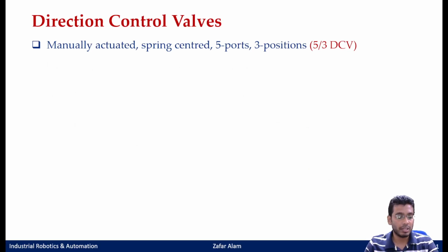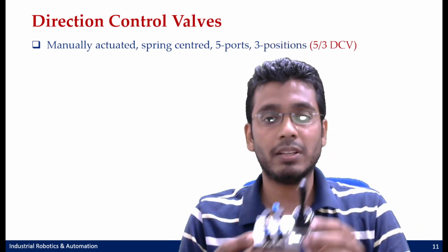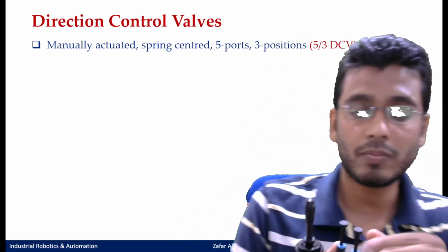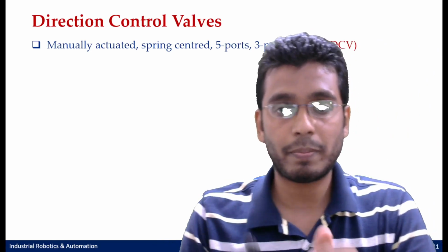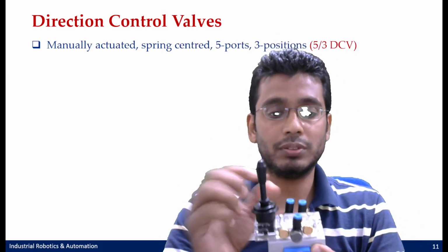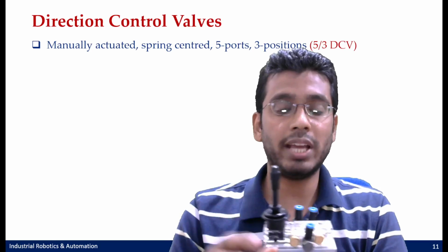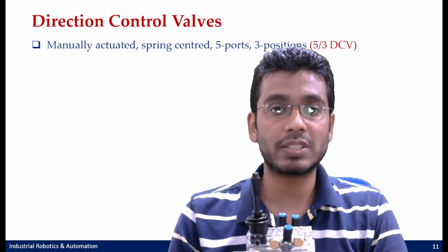Okay, so again I have another element here to just show you my exact valve. This is the exact valve that I have shown you. That means this is actually manually actuated, spring centered. It is having 5 ports and 3 positions.